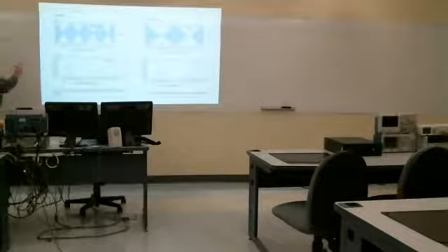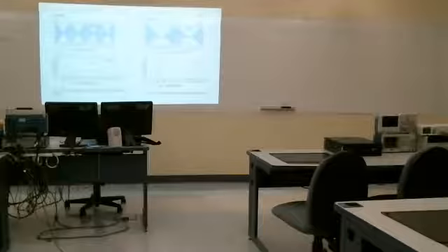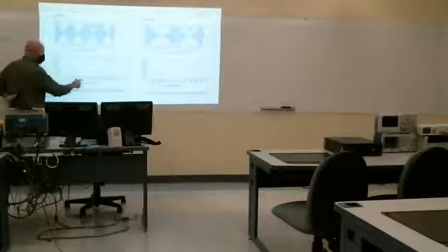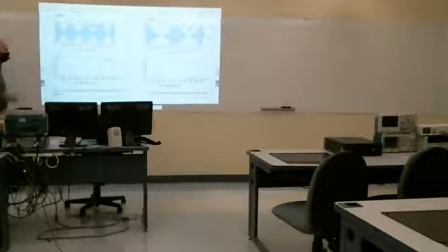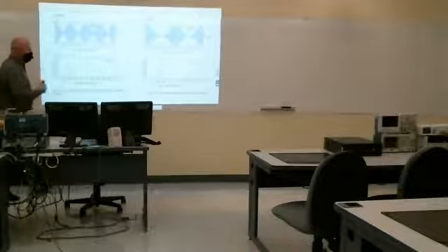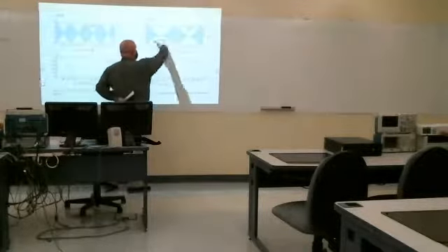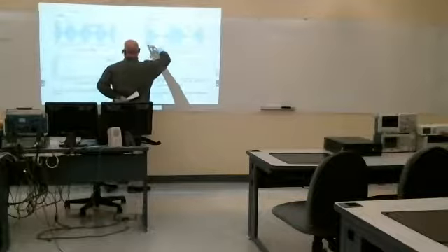Okay. And now with the tone, you know, double sideband, if you looked at the low frequency spectrum of a 1 Hertz tone, it's got components at +1 and -1. We multiply that by our 50 Hertz carrier, what we get is 2 impulses at 51 and 49. Okay, that's what we talked about last time. And that's what's showing up here. We get these 2 impulses at 49 and 51 Hertz. The only difference with AM, it's the same signal with the DC offset now, and so it looks different.